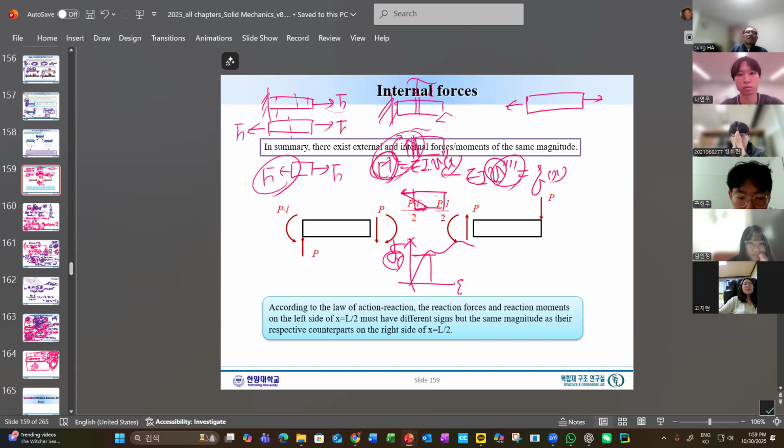So all the stress has to be less than this. So we should design considering a safety factor this much. So the stress has to be less than here, or as the loading and unloading like this. So if we have the load like this, a vertical load and the maximum here, the stress should be within these ranges. That's what we do.